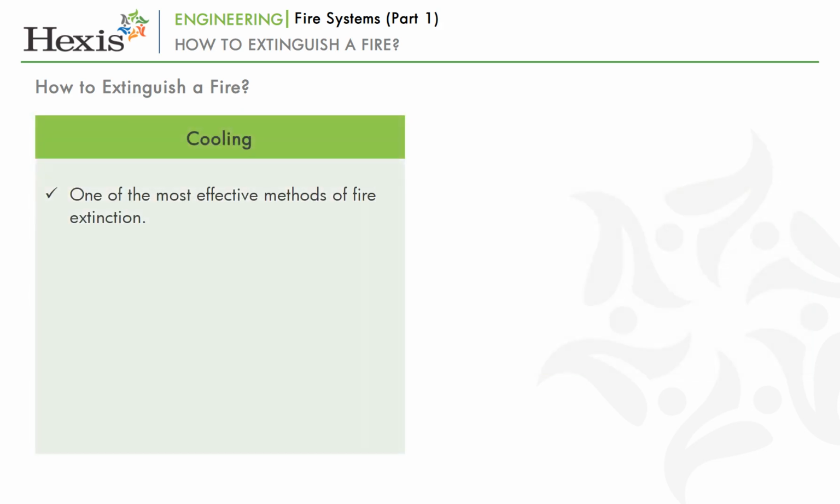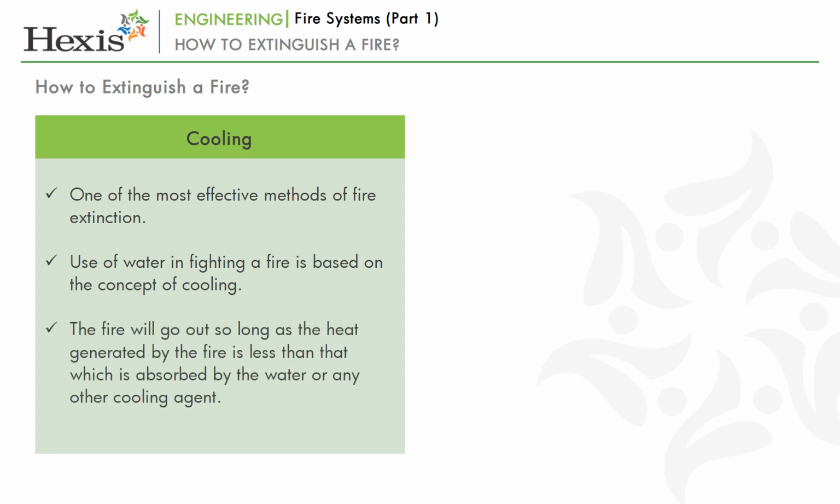Cooling. Removing the heat is one of the most effective methods of fire extinction available. Use of water in fighting a fire is based on the concept of cooling. The fire will go out so long as the heat generated by the fire is less than that which is absorbed by the water or any other cooling agent.